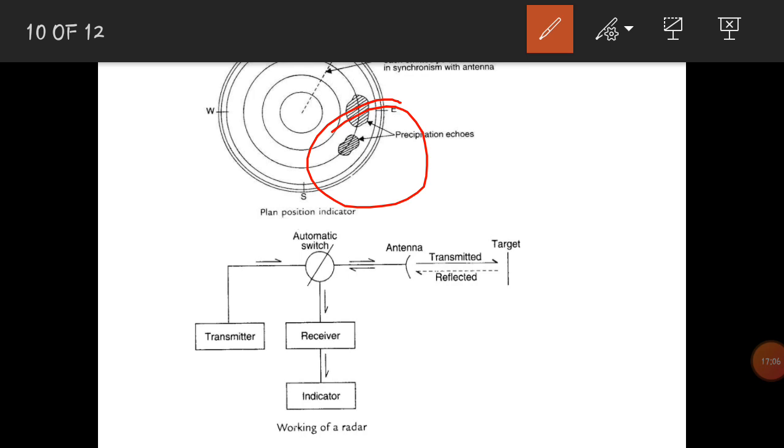Scatter and attenuation of microwaves by precipitation targets can be the basis for estimation of precipitation. Currently, reflectivity data, either alone or in combination with rain gauges, are considered most practical for operational measurement of rainfall over large areas.